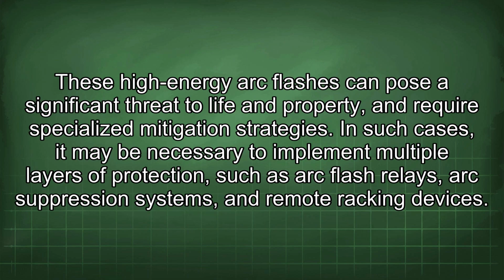These high-energy arc flashes can pose a significant threat to life and property and require specialized mitigation strategies. In such cases, it may be necessary to implement multiple layers of protection, such as arc flash relays, arc suppression systems, and remote racking devices.